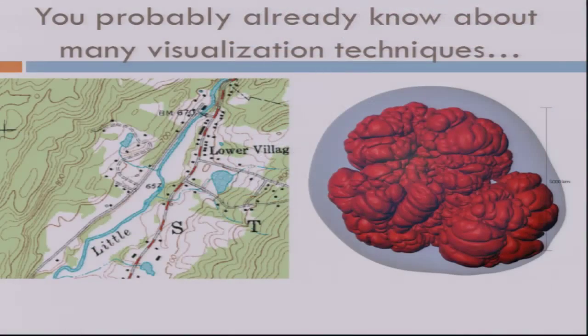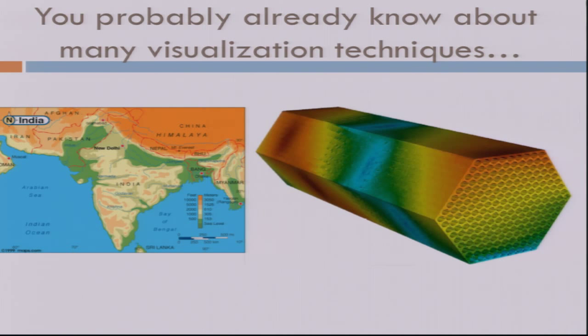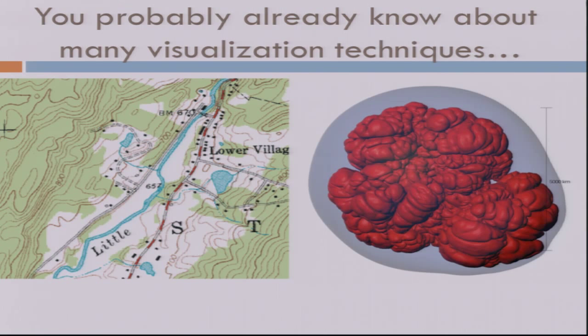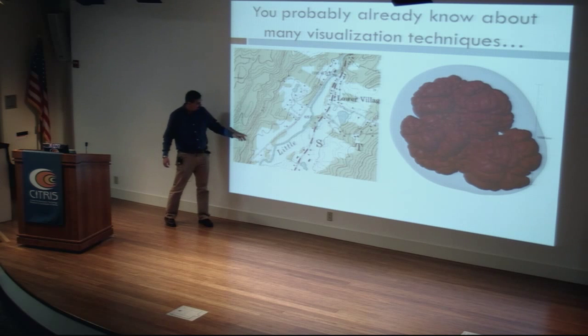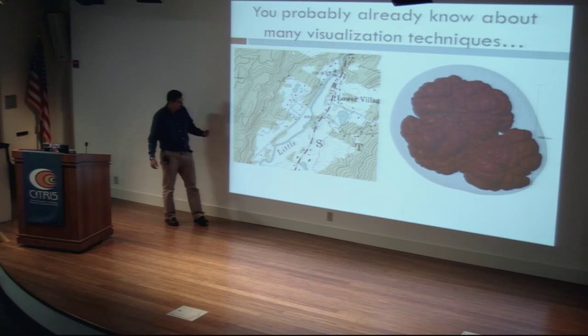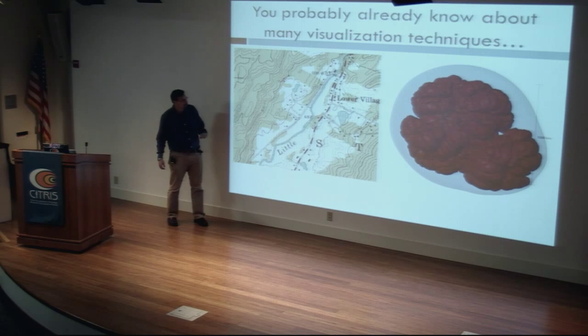So this is another way to look at elevation, where in this picture, we were doing pseudo-coloring and looking at the elevation at every point in that region. Here we're looking at a map, and the map has overlaid on it elevation lines. And so this line right here corresponds to 700 something, presumably meters. This line right here corresponds to 800 meters, and these other lines in between correspond to 720, 740, 760, and 780. So each of these lines is an isoline. It's a line of constant value for the elevation field.